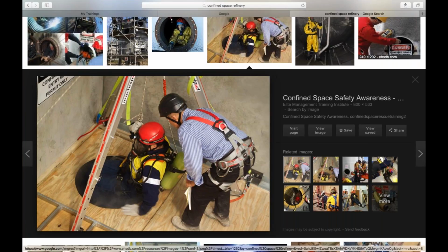We have to have a medical evaluation survey. We have to survey their near medical facilities to make sure that we know where near medical facilities are. We have to have a written emergency medical procedure, okay? And it's got to be prepared for handling accidents at a minimum with minimal confusion. If the job's located far from medical facilities, like we said, at least one person's got to be first aid CPR trained. In most situations, they will accept Medic First, American Red Cross, and American Heart Association, and a couple others. Just make sure with your client or in your area which first aid CPR AED training is acceptable. Okay.